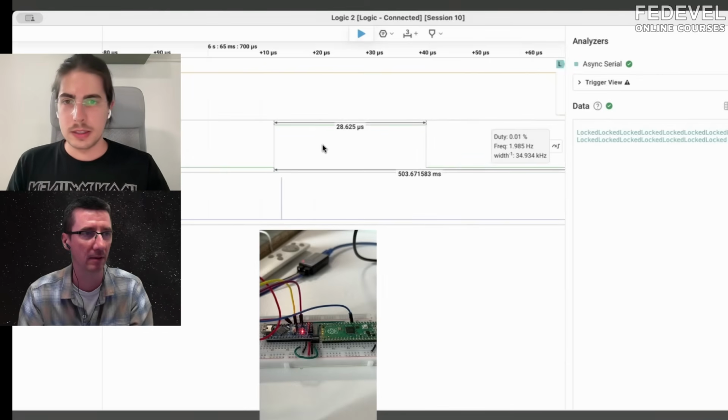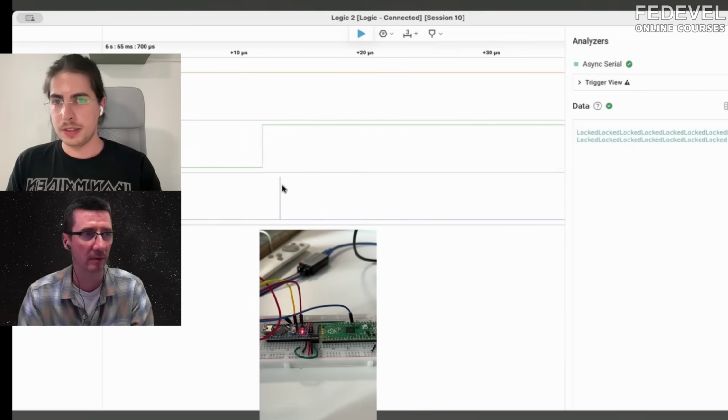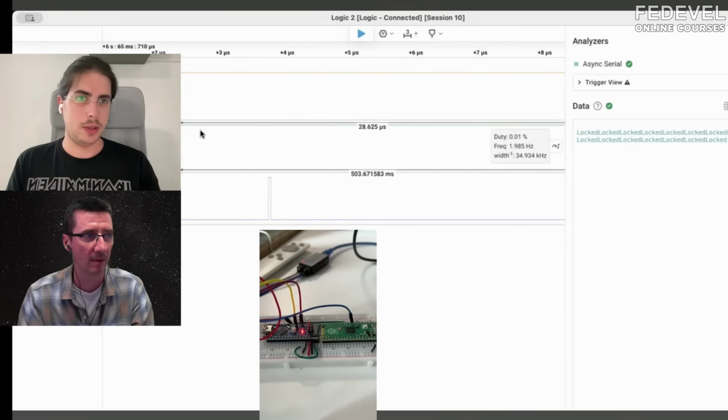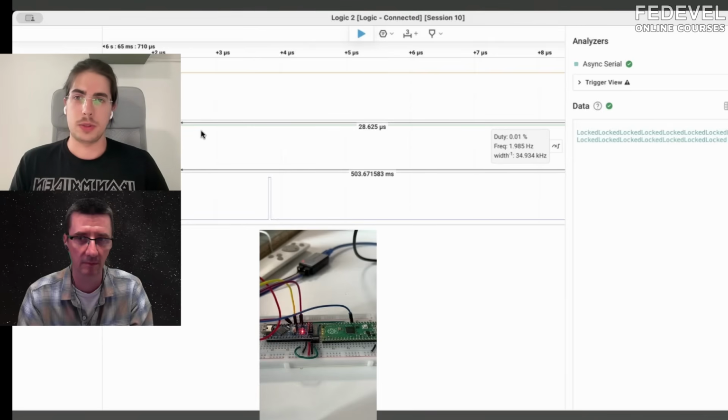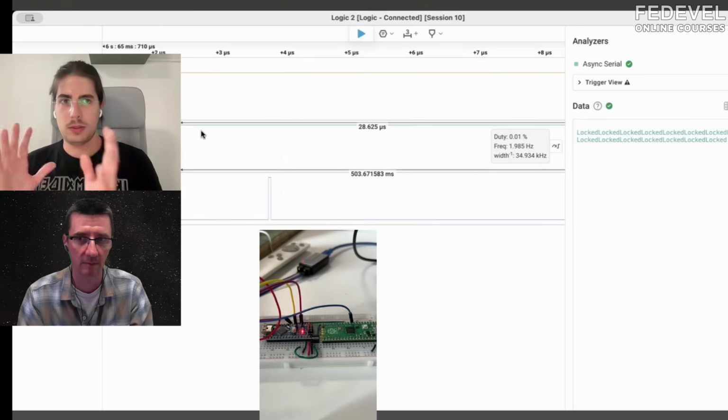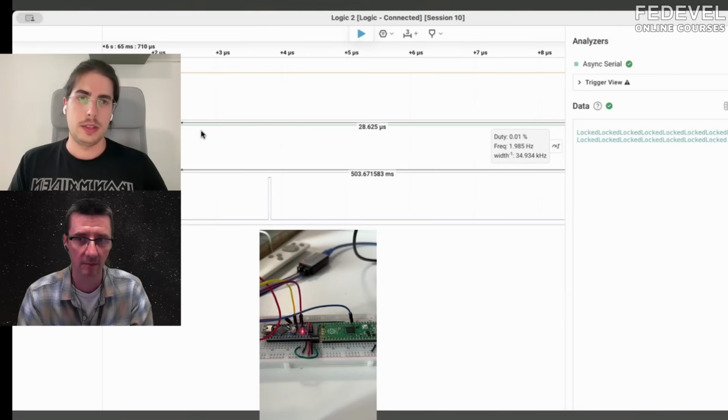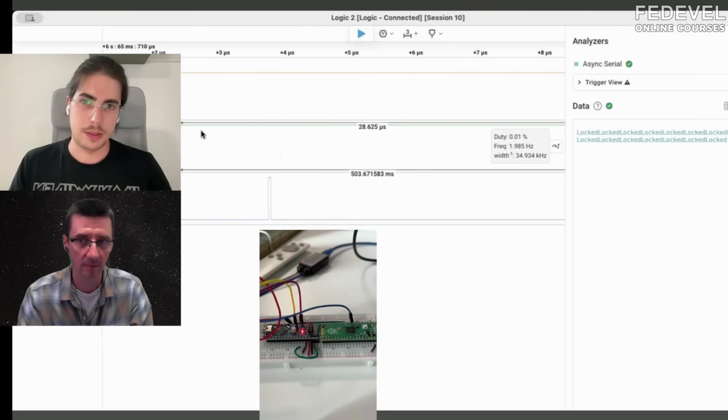Yeah. Okay. Yes, so this is another thing I did to make it easier to attack. Basically, I put a GPIO high and low before and after the critical operations. And you would always do this even on a real target, because usually you can get a dev board for it, for instance, and then you can program it with whatever you want. And you can add something like a GPIO trigger so that you know when certain things are happening during boot time. And then you can relate that on the real product where you don't have the firmware. Then you can apply all this knowledge that you have gained from the development board on the real thing.